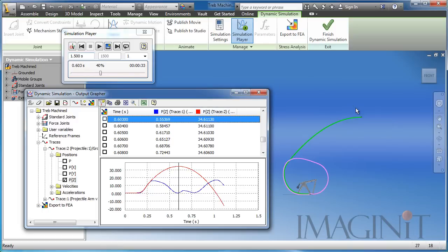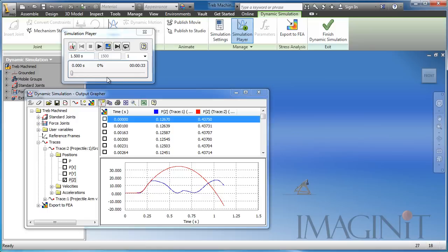And in this particular case with the ball, the model is put at the actual time step where the ball is at its highest peak in its trajectory. So very nice. We can actually define certain time steps. And what dynamic analysis allows me to do is export these time steps to FEA and run an analysis. Now, that's our next step.